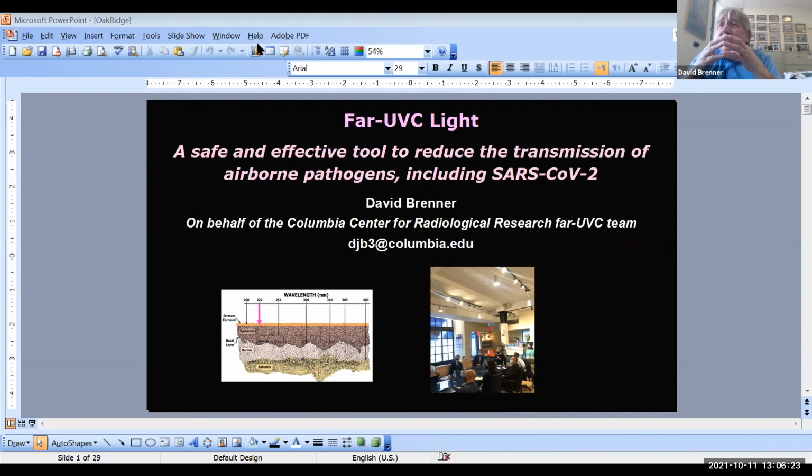It does depend to an extent on the particular lamp design. Ushio, for example, one of the manufacturers, makes a big deal about their ozone production being super low. But it's an issue, and for any new lamp that comes on the market, one of the big things will be to test for ozone. But to date, at least, none of the lamps that we've tested have produced in the air anything like the EPA limit.